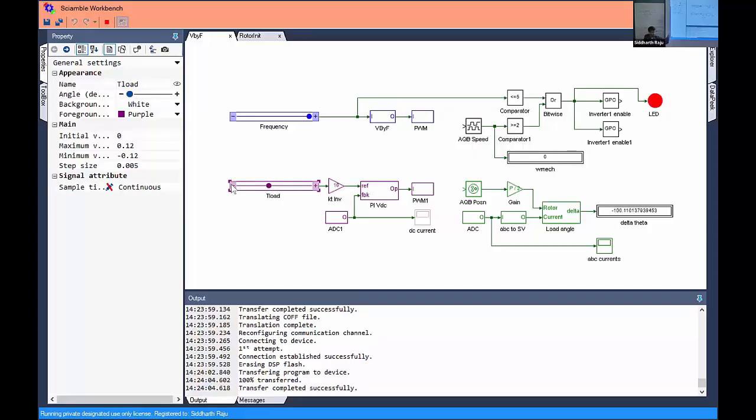When you connect to a grid, now this is okay because this has a current limit on the inverter, which can limit the current going through it. But as soon as the rotor comes to a stop, what happens to the EMF? EMF goes to 0. So you're applying this whole grid voltage across a tiny resistance and some tiny inductance. That's going to cause a huge amount of inrush current, which will either burn the coil or it will demagnetize the magnet, because you'll put a magnetic field so large in the opposite direction depending on the rotor alignment that you can completely demagnetize the magnet.